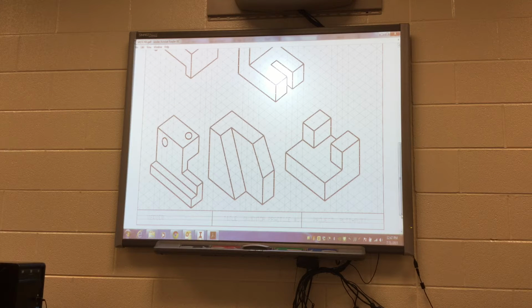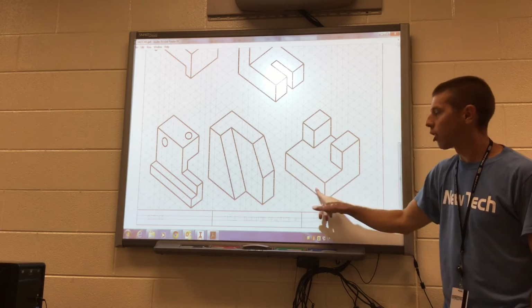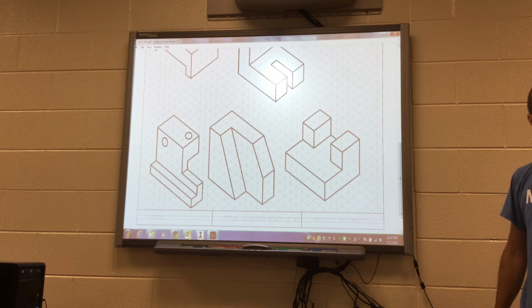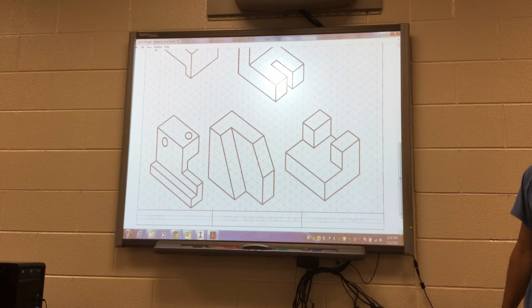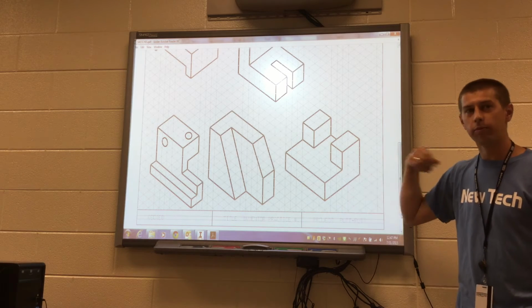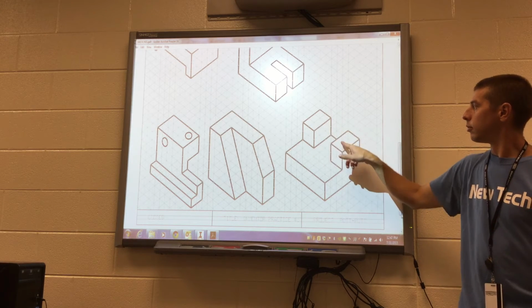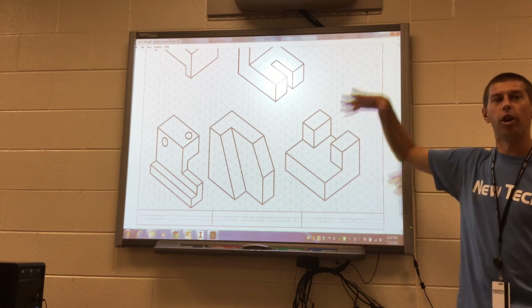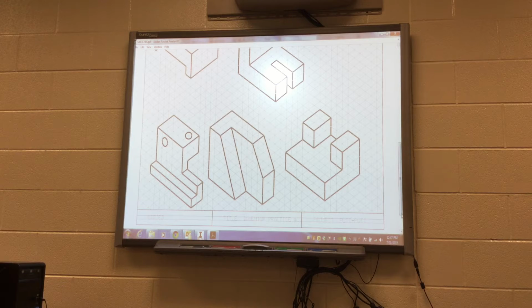Here, what will we do on this one right there? You draw the rectangle. Which rectangle? On the front, right, or top? Front. The front, so you're going to draw this rectangle right here and extrude it back. And then what would you do? Then you go to the top, okay, on the top, and draw a rectangle wherever you want. And then you would draw these 2 rectangles and extrude those up. That's one way to do it.